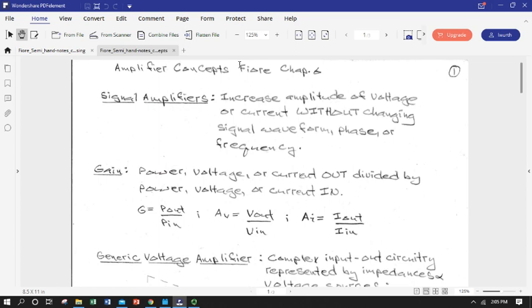Up till now, we've been concerning ourselves mainly with bipolar junction transistors, and we've covered concepts like a Q point, or a collector current versus collector emitter voltage drop operating point of the transistor itself, and the amplifier circuit built around it. We've looked at DC load lines and looked at what the maximum collector current we can get if there's no voltage drop collector to emitter in our transistor, and at the other end of the load line, what the maximum collector to emitter voltage drop would have to be to stop all of our collector current.